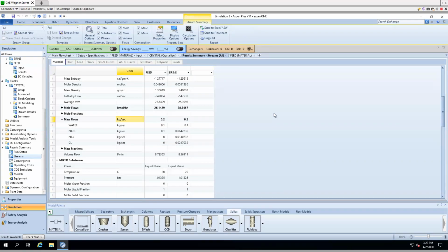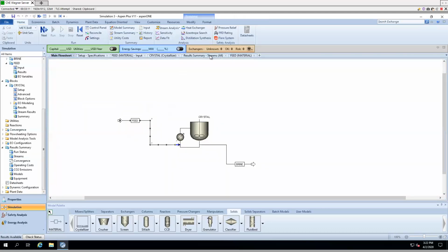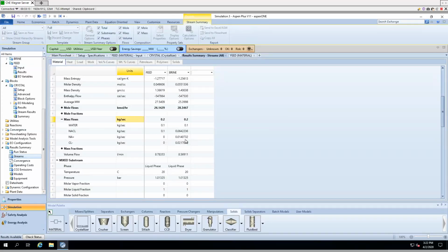Okay. And then as far as if we wanted to produce more solid, that means there's less dissolved salt, right? Exactly. And that means there would be more solid sodium chloride in this stream because less would become ionic. And so that's what I was talking about. Feeding less water is really the only option we can do because, and I can show you.